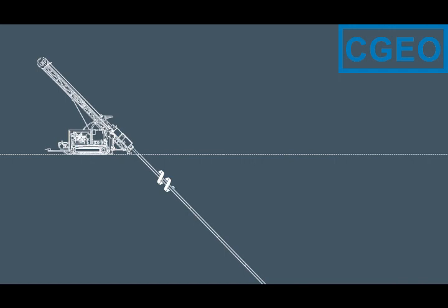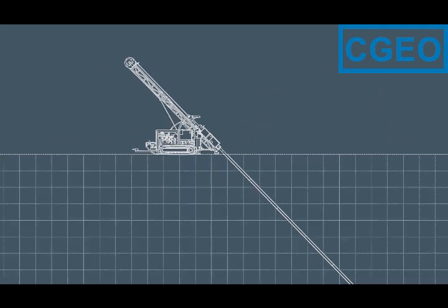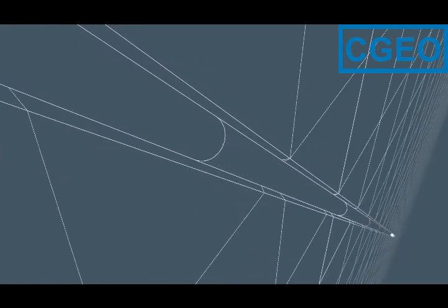The purpose of the drill rods is to transfer torque, rotation speed, and lifting or feed force down to the drill bit and the core barrel. In wireline drilling, since the inner tube assembly is sent through the drill rods, the inside of these rods must be produced with a high quality. Therefore, each wireline core barrel dimension requires the same drill rod dimension.